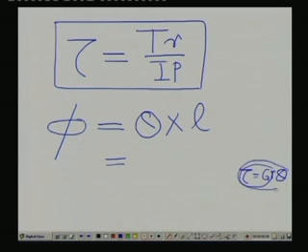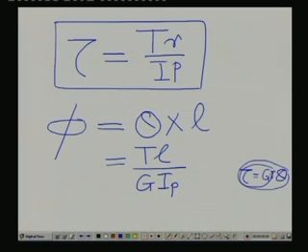This replacement will give us theta equals T L by G into I p. You got the point? I am not going to evaluate it, you can simply substitute this value of theta from here, and tau by G r comes out to be this particular formula. So, we get phi equals T L by G J.